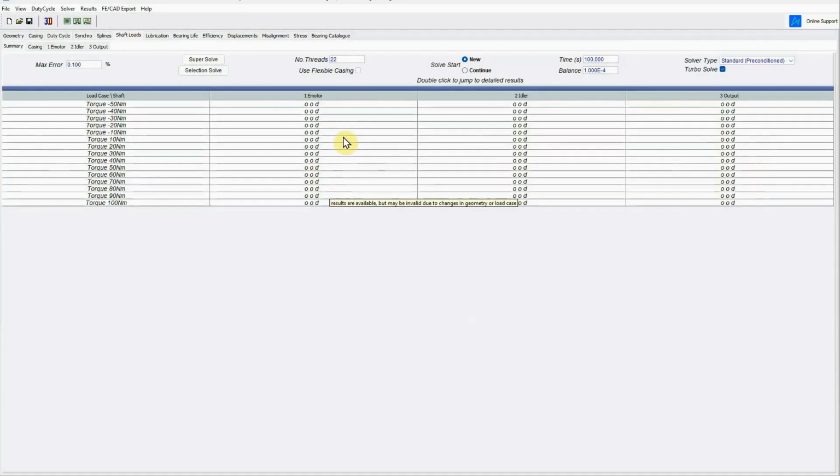so there are 3 shafts, each with 2 bearings, and it will take into account the shaft deflections from the applied gear forces at every operating condition. So we have about 15 different load cases across 3 different shafts, so we have to solve all of this matrix of solutions.